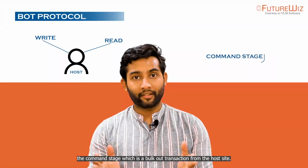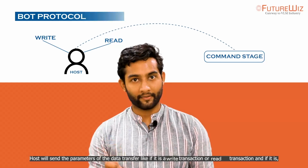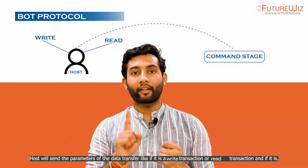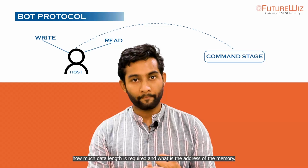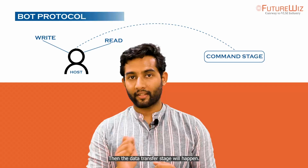In the command stage, which is a bulk out transaction from the host side, the host will send the parameters of the data transfer, like whether it is a write transaction or read transaction, how much data length is required, and what is the address of the memory. Also, it will add a BOT signature value. Then the data transfer stage will happen.